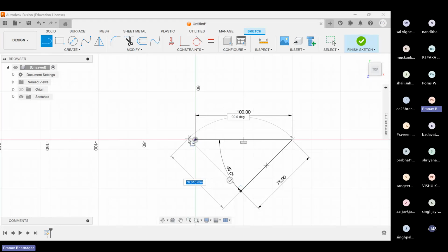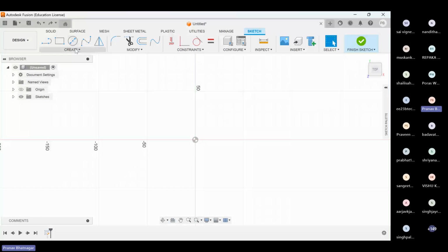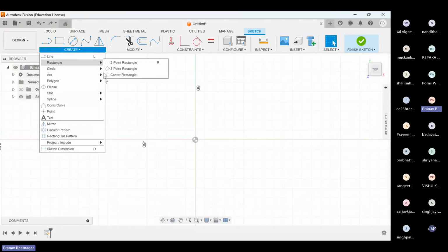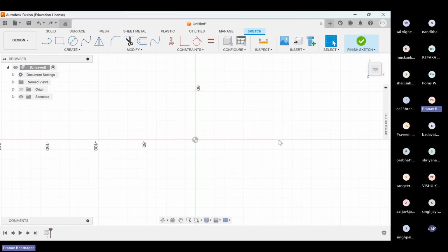This is a very intuitive software. If you want to make a triangle, even if you hover close to this point, it will just jump to the point, and there you go, you have a triangle. The blue color which appears inside shows when it is a closed shape. This is useful. So this is how you work with a line. By the way, the shortcut for line is L. If I just press L, it will jump to line and I can start making shapes like this. Very simple, nothing complicated here.